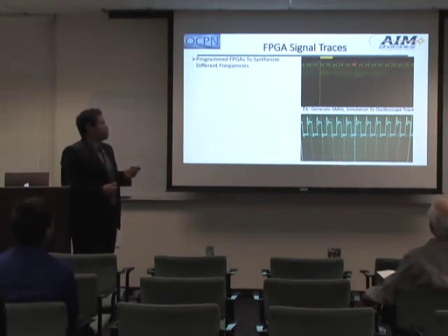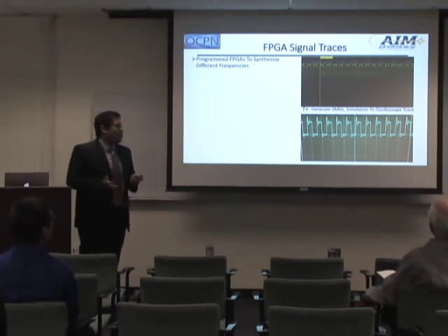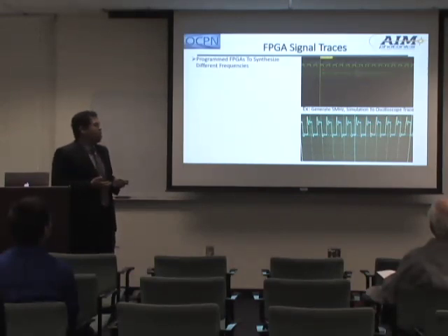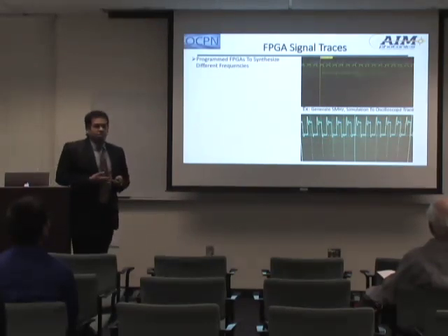Using a 100 megahertz frequency clock reference, I've been synthesizing in this example a 5 megahertz signal. And this is the simulation. The process goes from writing the code to simulating it, to then assigning it to the FPGA and connecting that to an oscilloscope to determine just how well the code translates to the actual hardware. And this is the oscilloscope trace of this simulation. It looks a little different, but they are both 5 megahertz waves. So the process has been done from beginning to end.